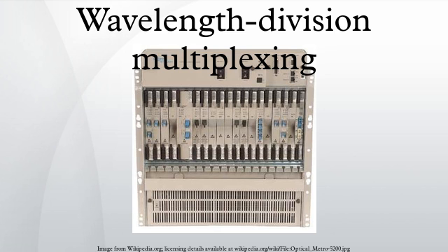An intermediate line repeater is placed approximately every 80–100 km to compensate for the loss of optical power as the signal travels along the fiber. The multi-wavelength optical signal is amplified by an EDFA, which usually consists of several amplifier stages. An intermediate optical terminal, or optical add-drop multiplexer.